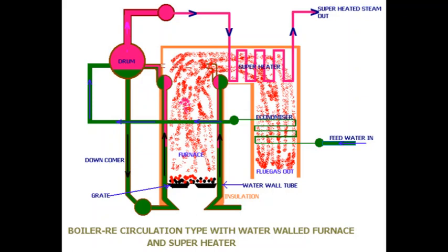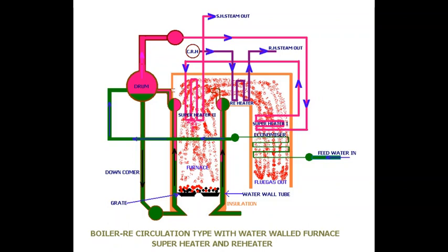Besides that, depending upon the requirement, it was observed that the fuel which was usually burnt at the bottom of the furnace in a travelling grate did not get completely combusted, and there is loss of fuel energy with the ash.